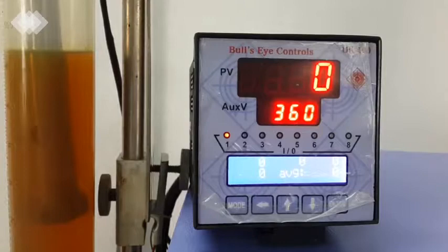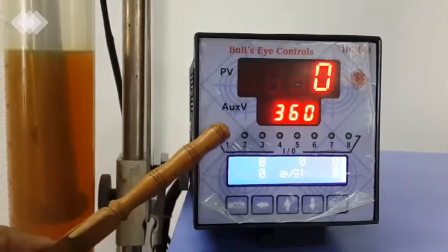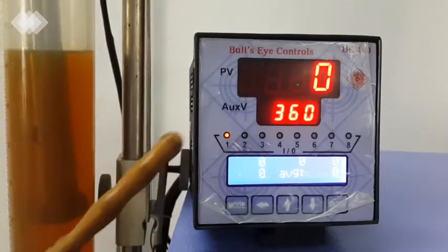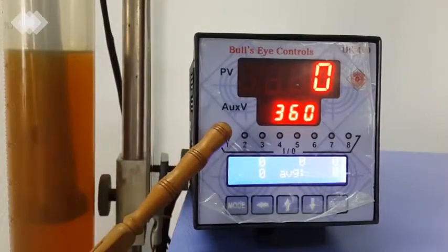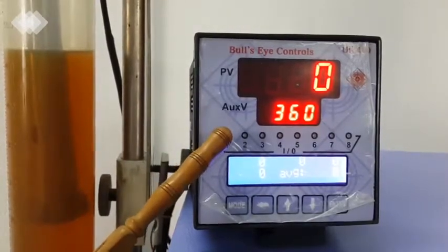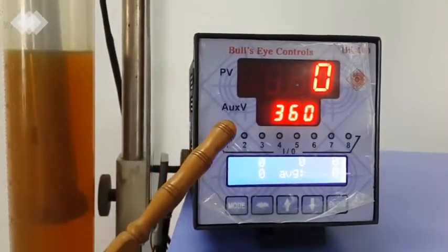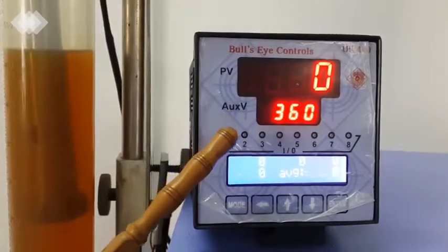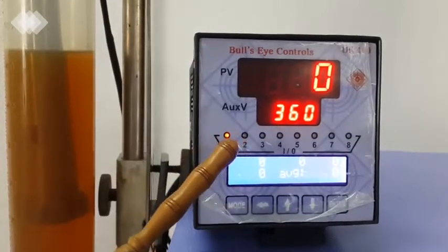Okay, you see the sampling is taking place. So this number 1 LED is for the air solenoid. Once this is on, in the element, the piston goes up. Okay, this is the air solenoid. Now, after the sampling period is over, this signal will go and the piston will drop. Just wait, we'll see it again. The sampling period is set for 30 seconds, so after 30 seconds it's supposed to come down.